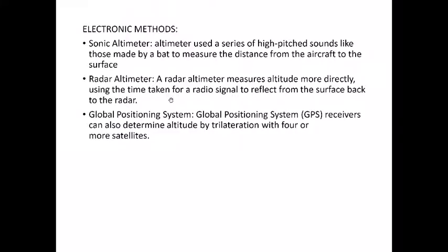Nowadays, we have this very high precision instrument called LiDAR, light detection and ranging. So it basically works on the same principle. It flies over any area whose elevation differences you want to find out. It sends out multiple beams of laser, and then it can give you a complete profile of the area. We call that a digital elevation model.